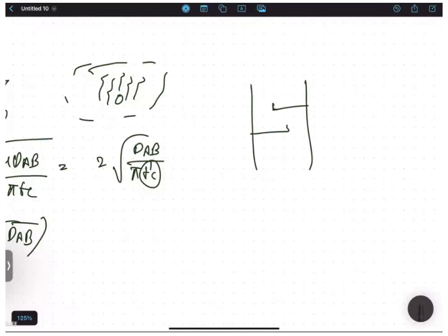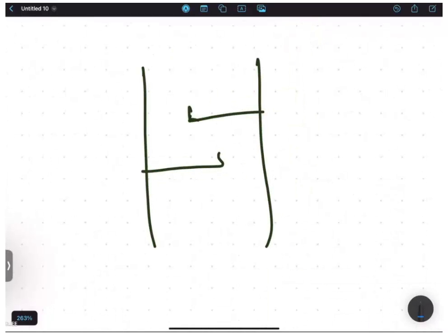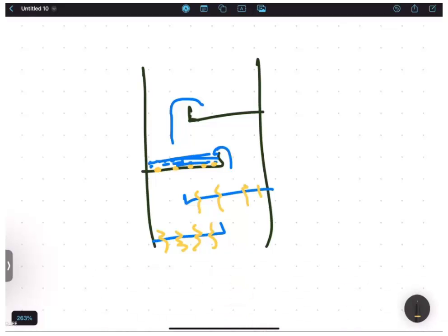So in the distillation tower, what happens? Please understand. In the distillation tower, your liquid comes from the top. Suppose liquid comes to this tray. So this tray will be full of liquid, and once it reaches above the weir height, it will flow down again, and other trays are there. Your gas will flow from here. You know different types of trays, bubble cap tray, sieve tray. So sieves are there. From here, gas will bubble through the liquid.